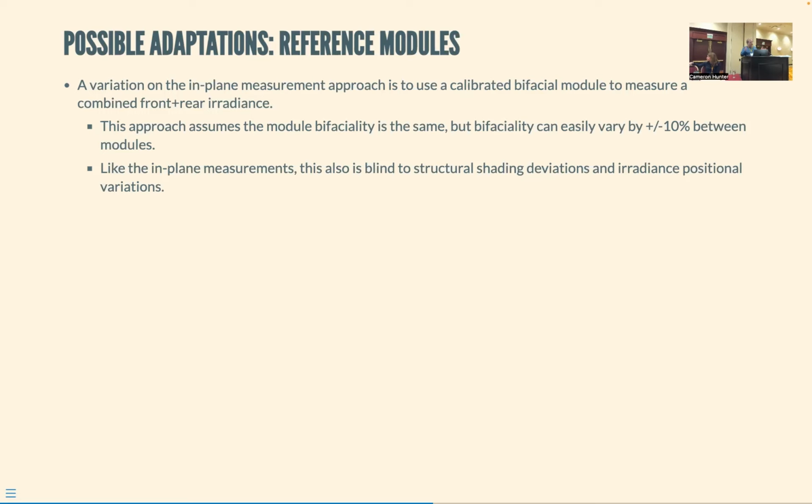If you place it next to a support post, you'll have a different shading situation than you will if you're halfway between support posts. So your placement, you end up needing to put a whole bunch of these reference modules in if you wanted to do a good job of characterizing what was available to the array, which is expensive and isn't usually how things work.